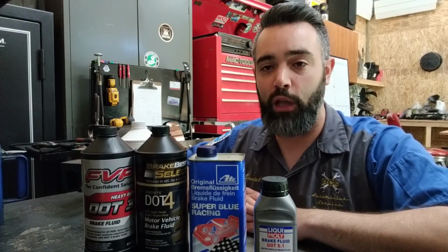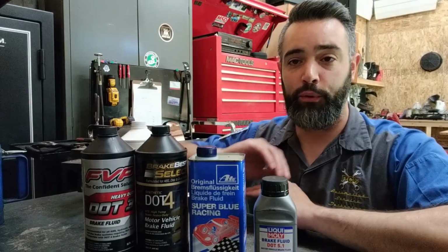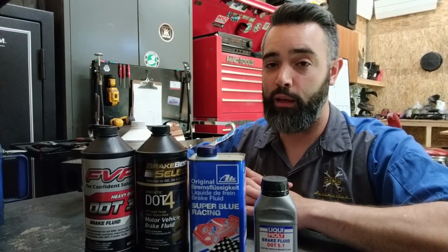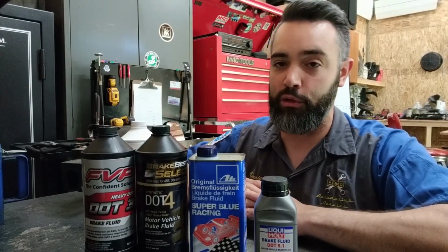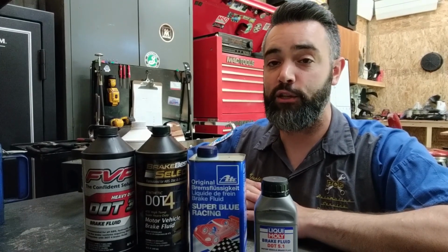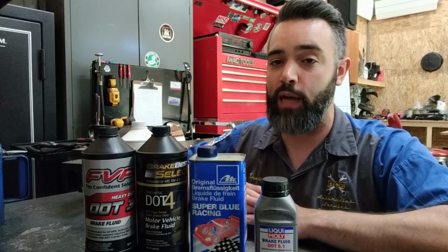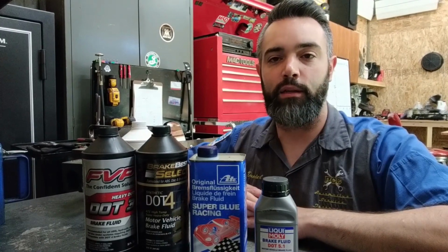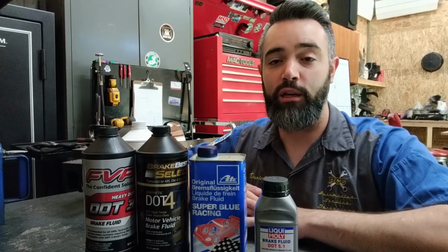So when we reach our low boiling point spec for the fluid, regardless of what type of fluid it is, it will have a dry boiling point and a wet boiling point. Dry boiling point means when you open the container and it is sealed, that fluid has not been introduced to moisture. It is therefore considered dry. The boiling point decreases until it reaches its wet boiling point specification for that fluid, at which time that fluid needs to be serviced and replaced with new fluid. Fluid that has absorbed moisture will continue to absorb moisture over time, and that boiling point will continue to decrease.